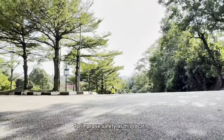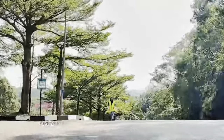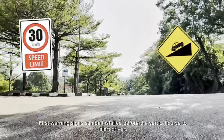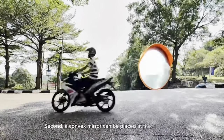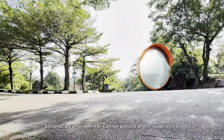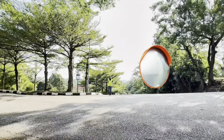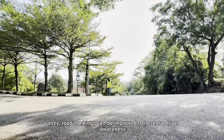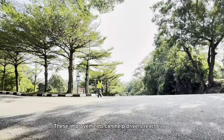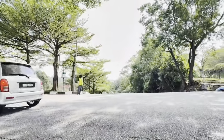To improve safety at this location, several mitigation measures are suggested. First, warning signs can be installed before the vertical curve to alert drivers. Second, a convex mirror can be placed at the road section to help drivers see approaching vehicles more clearly. Lastly, road markings can be improved to increase driver awareness. These improvements can help drivers react earlier and create a safer driving environment.